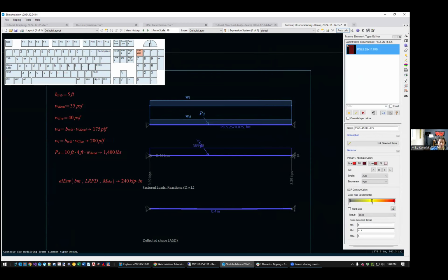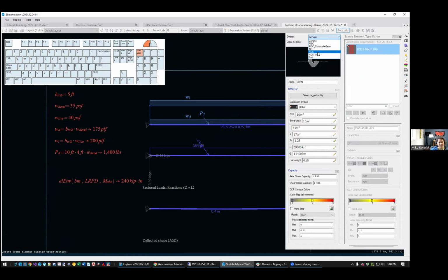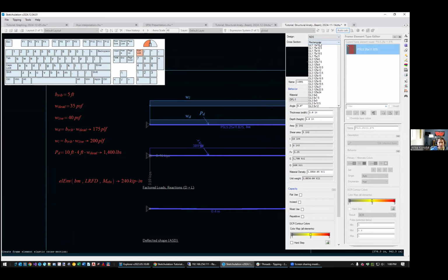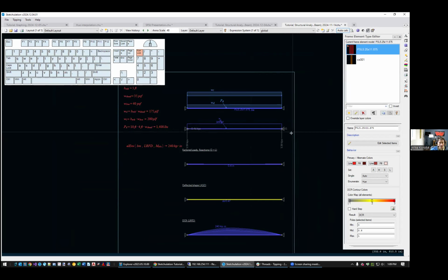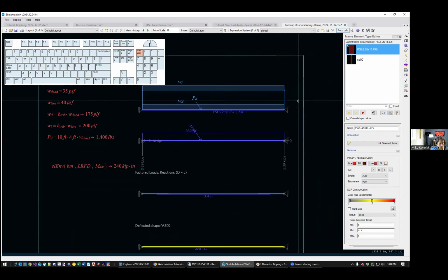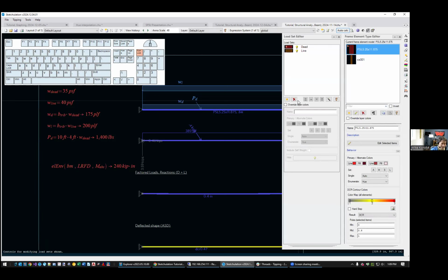And we were just doing a wood beam design. We pushed the new button and we went into NDS and dropped down until we got the shape that we wanted, and then picked out the material that goes along with the shape, and we made our new cross section. This one was a PSL type of beam, and we showed how you can auto create, I forgot to mention this, auto create the load sets and the load combinations.